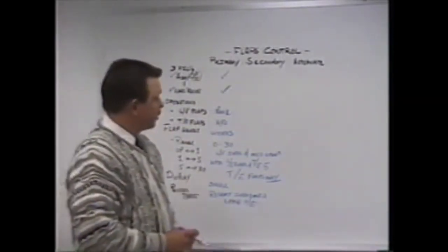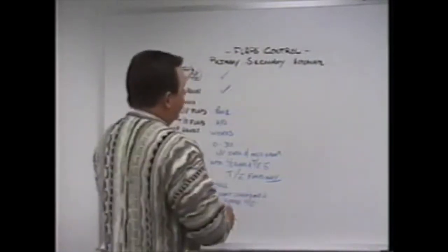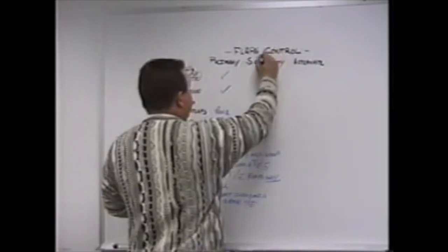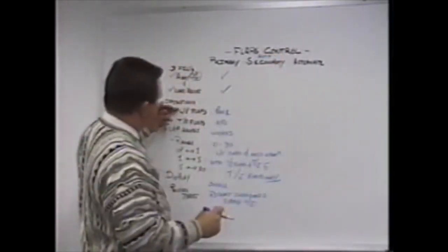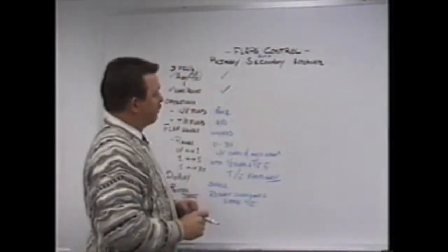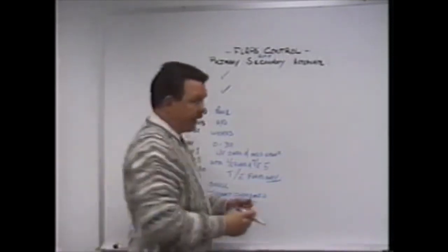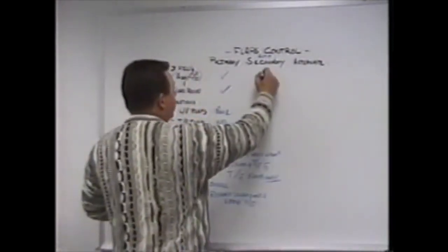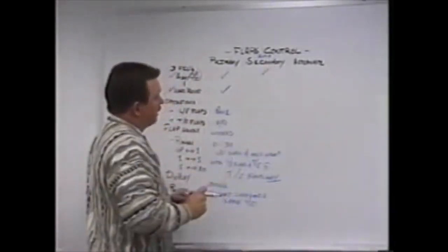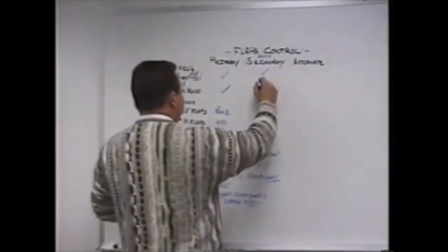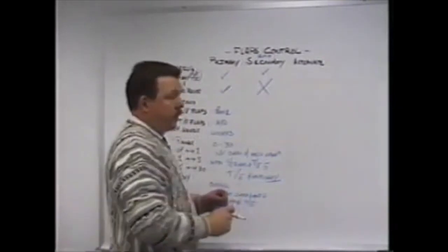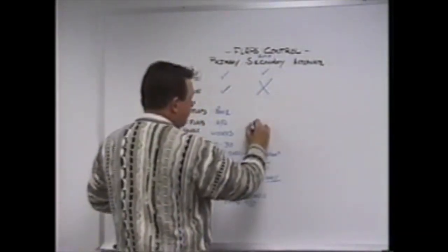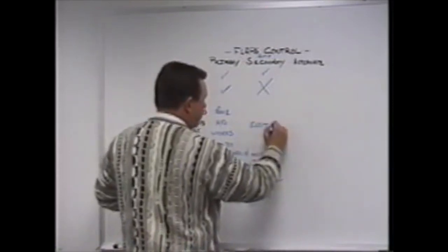Single vertical tape display. Secondary mode of flap operations happens automatically. If you encounter a problem with the leading edge pneumatic or trailing edge hydraulic flap drives, the secondary function will automatically kick in. The 3 flap control units still work. You do have asymmetry protection on the leaders and the trailers in the secondary mode. However, you do not have load relief, because the source of power to operate the trailing edge flaps in the secondary mode is electric motors.